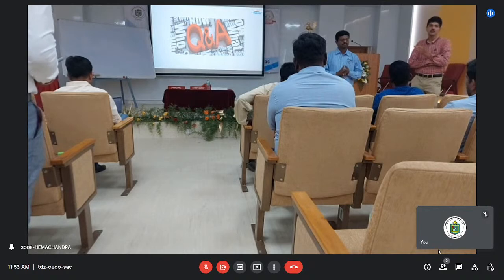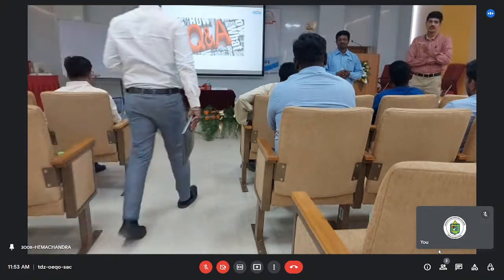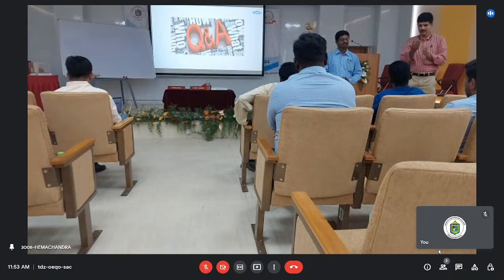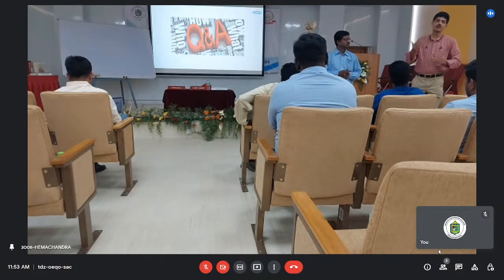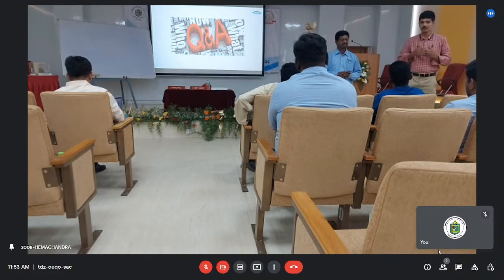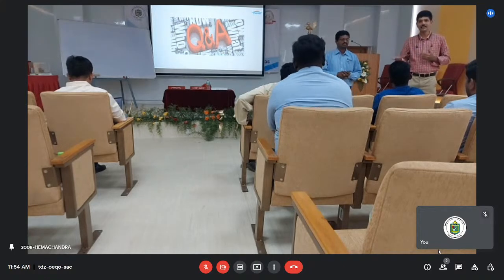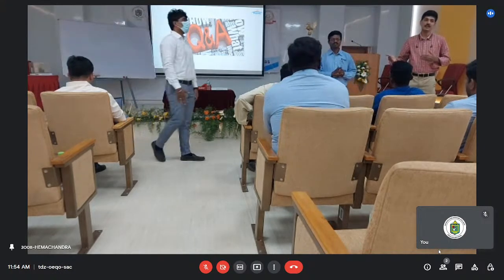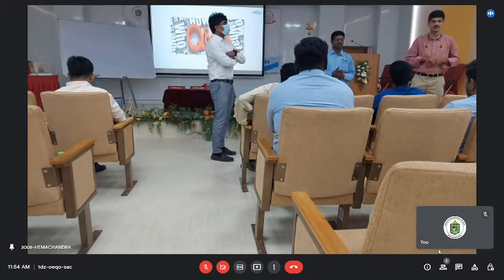Or else, what we normally used to do in a brick wall is cement, sand, mortar, light cement, sand, polymer, apply it, give a putty finish, and then waterproofing on top. On a direct brick wall we should not apply any waterproofing. Either you can give a sand-faced plaster or do it like this, and after that you can apply the waterproofing coating and then plaster.